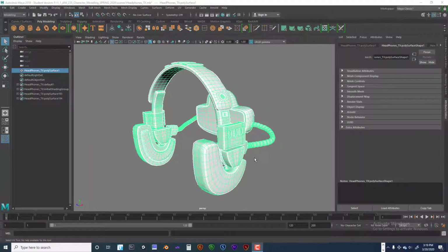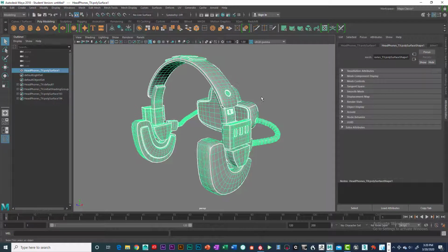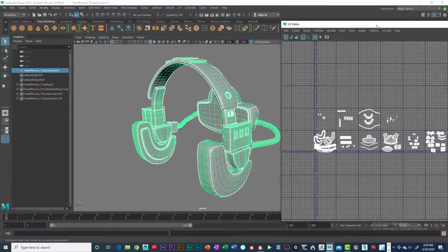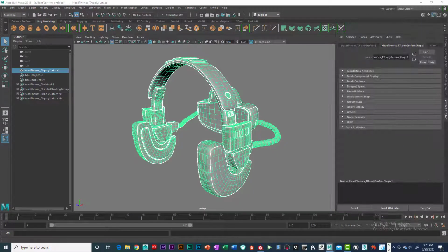This is Project 2, Lecture 10, and we're going to talk about how to apply the Substance Painter maps that you created onto your object. So let's go ahead and do that. Select your object, and let's double check the UVs, make sure they're all there, and they are. So let's go ahead and move that over.